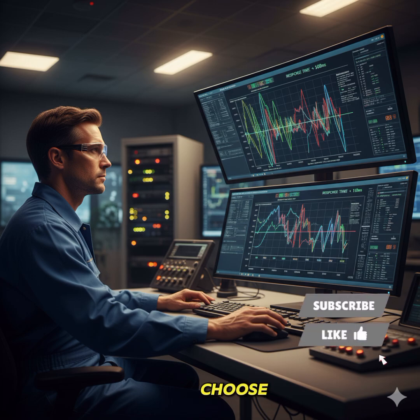Choose DCS if your process is continuous and located within one plant. You require instant control, redundancy, and reliability. You handle critical process variables like pressure, flow, or temperature. Remember, the goal isn't to decide which one is better, but which one fits your process.